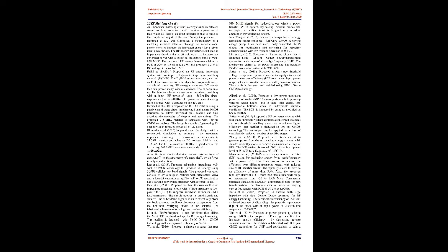3 Components and techniques of energy harvesting. 3.1 Rectenna. Rectenna is a special type of rectifying antenna that is used to convert the induced AC by the electromagnetic energy to DC. Usually the rectenna is made up of a simple dipole antenna with the RF diode connected across it. Normally the Schottky diodes are preferred because of their high speed of switching.